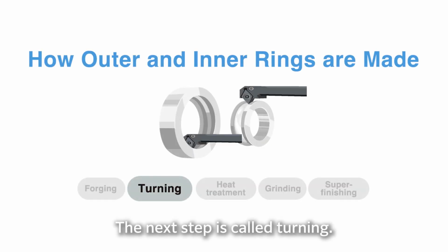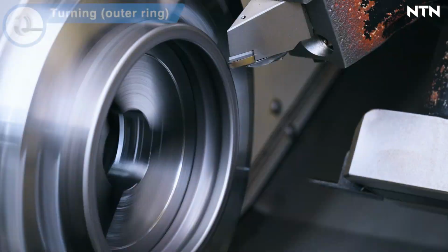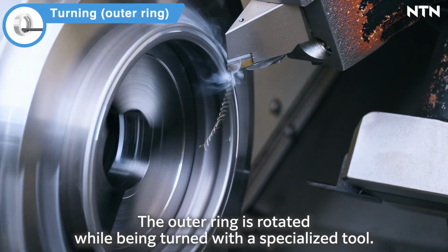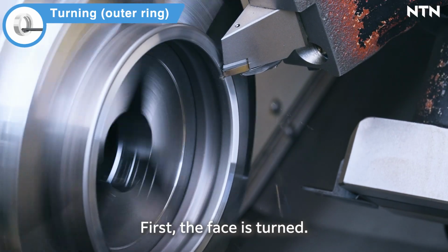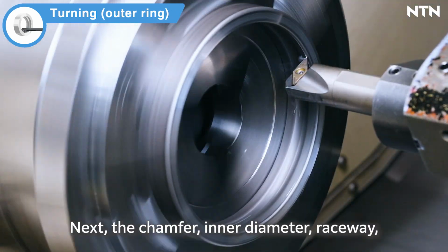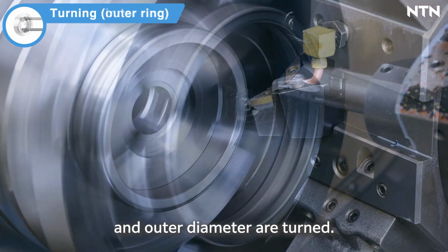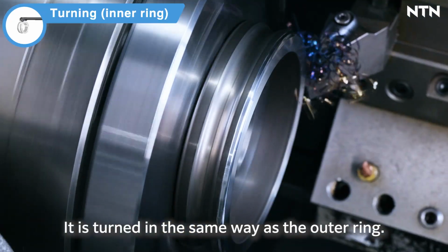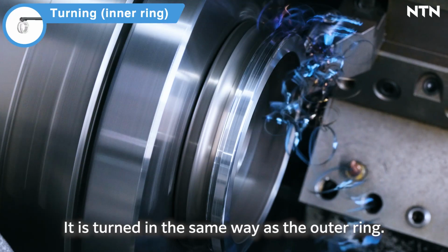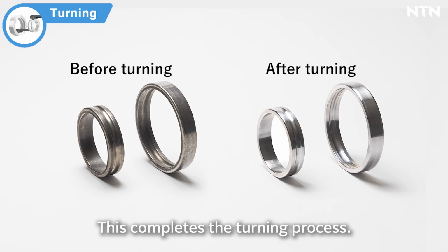The next step is called turning. The forged outer and inner rings are turned to cut a rough shape. The outer ring is rotated while being turned with a specialized tool. First, the face is turned. Next, the chamfer, inner diameter, raceway, and outer diameter are turned. Next is the inner ring. It is turned in the same way as the outer ring. This completes the turning process.